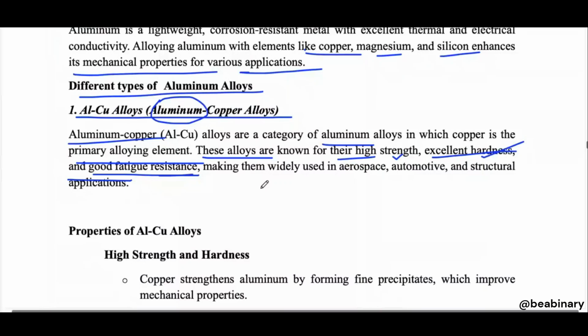So in dynamic load conditions, we have a different kind of scenario where the material fails very early compared to normal loading. With normal loading, the material fails when it reaches either the yielding point or the fracture point, the ultimate point. In ductile material we have the yielding point, and in brittle material we have the ultimate strength, the ultimate stress.